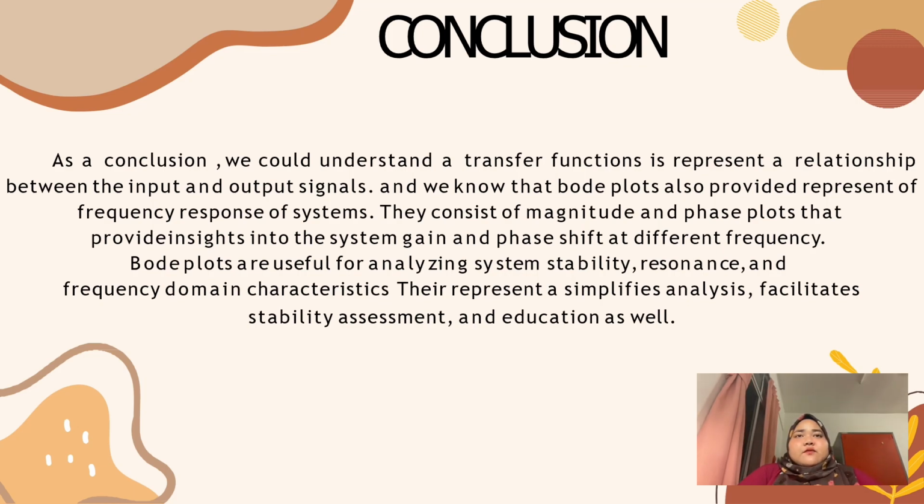By analyzing transfer functions and Bode plots, we can gain insight into system performance, stability, and frequency characteristics. We can identify critical frequencies, design appropriate compensators or filters, and optimize system response and stability. We can determine the transfer function, and we can also learn how to plot the Bode plot from the transfer function. Lastly, a Bode plot is a graph that represents the frequency response of a system. It shows the magnitude and phase of the transfer function as a function of frequency and can be used to analyze and design control systems.